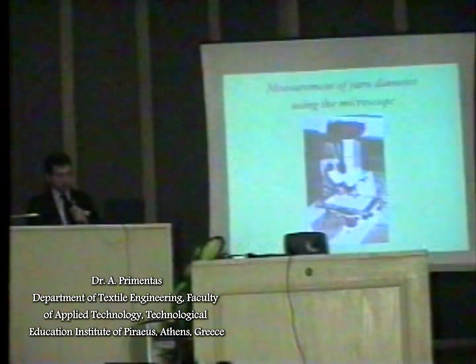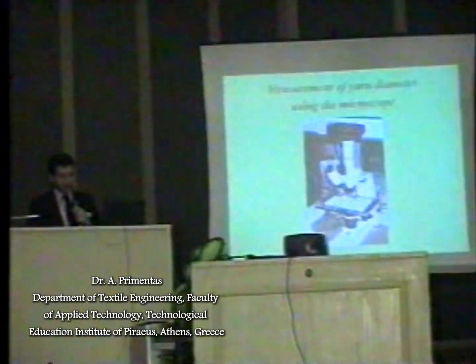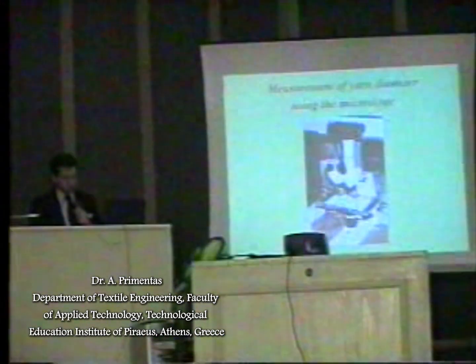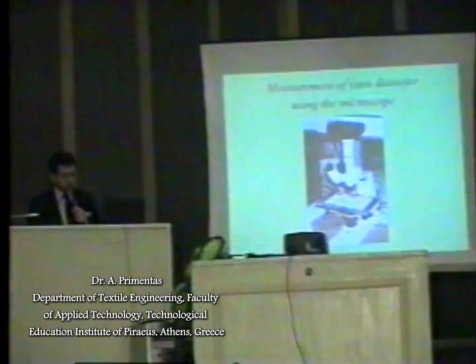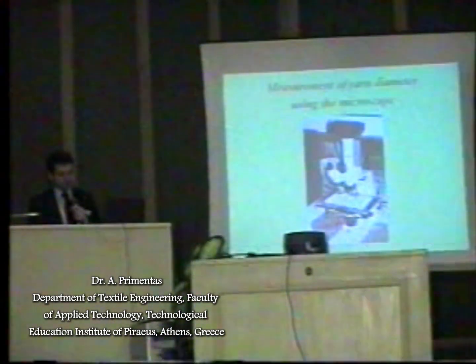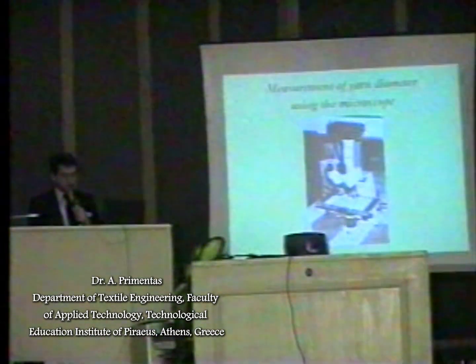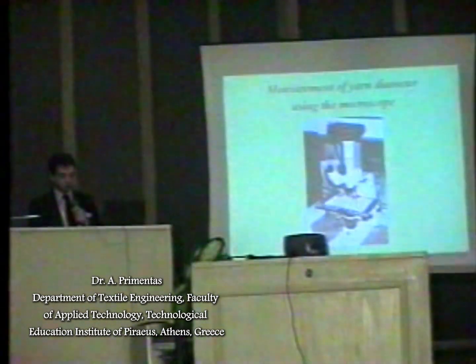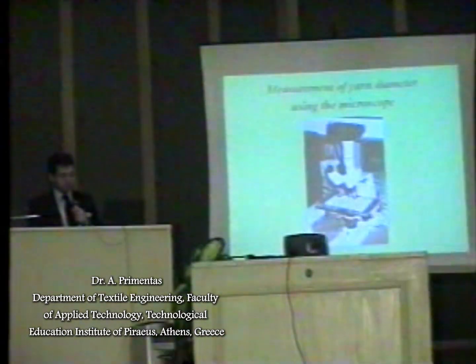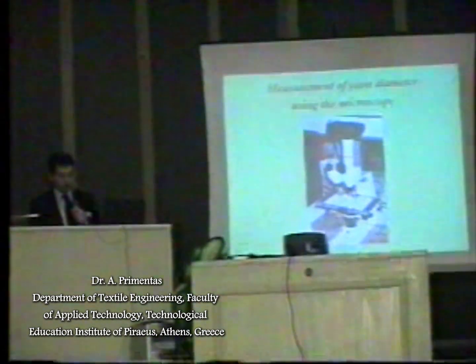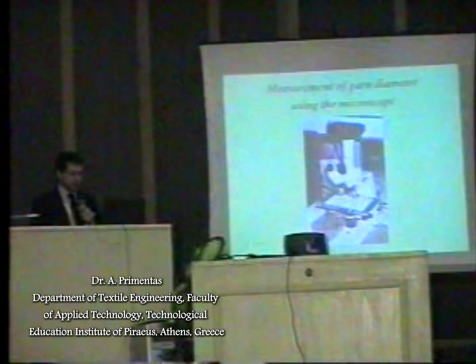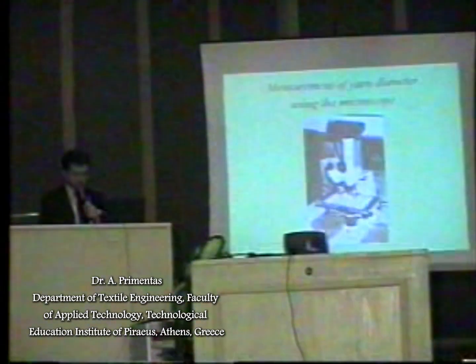Yarn thickness was considered the distance between the two sides of the yarn body as seen under the microscope, subjectively neglecting the zone of some protruding fibers. Diameter measurements were made in various places of the frame. The movement of the frame was made with great care to avoid any yarn or thread disturbance.